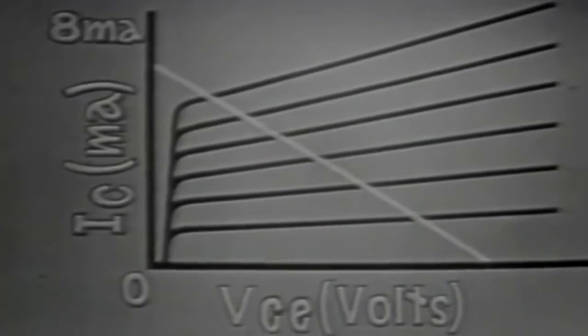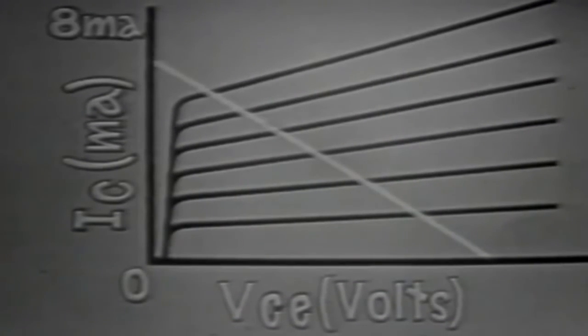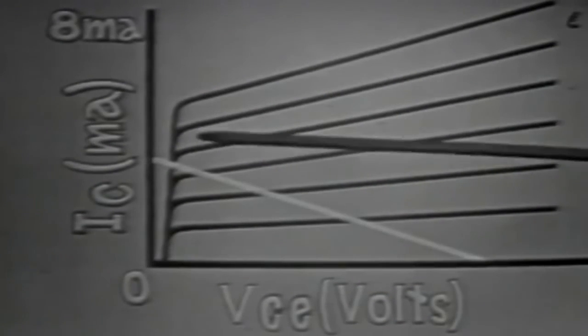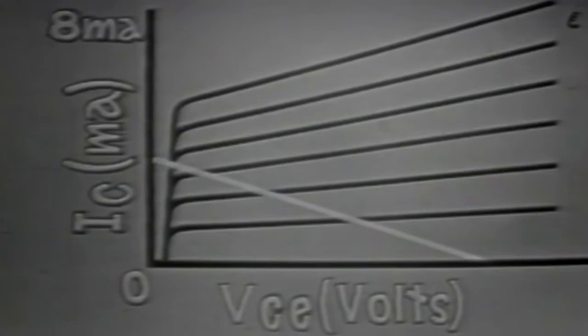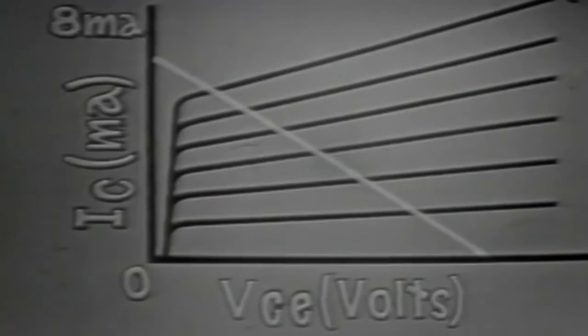We begin with a small resistor and increased it. The load line dropped to here. We had a decrease in current gain and an increase in voltage gain. If we started here with a large resistor, say 4K ohm, and decreased the resistor to 2K ohm, the opposite would have happened. Current gain would have gone up and voltage gain down. An important conclusion is that a current amplifier would have a relatively small collector load resistor and a voltage amplifier would have a relatively large collector load resistor.